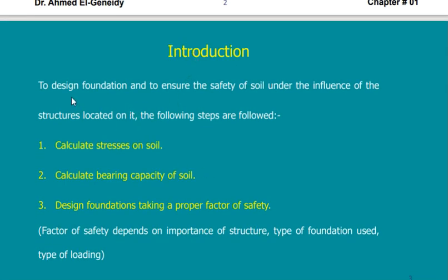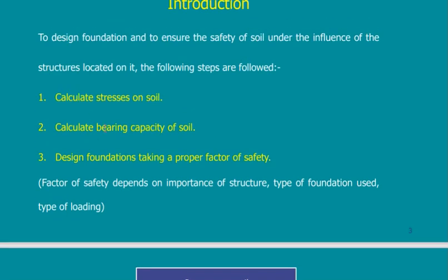Let's see what is written here. To design foundation and to ensure the safety of soil under the influence of structures located on it, the following steps are followed. Number 1, calculate the stress on the soil. Number 2, calculate the bearing capacity of the soil. Number 3, design foundation taking a proper factor of safety. So to design any building, I calculate the stress, see the bearing capacity of the soil, and design the footing based on this bearing capacity.